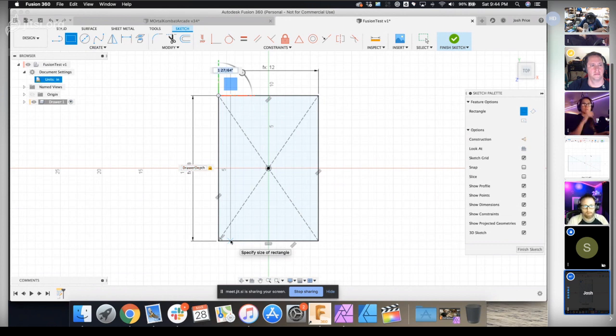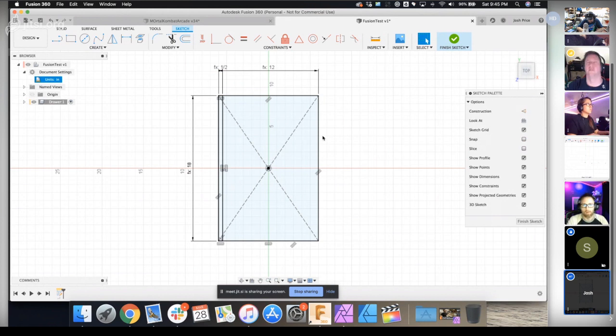I'm going to tab over. You could type in 0.75, or you could type in 3/4 because my plywood is 3/4 of an inch, or you can type in 0.5. That doesn't update. That's not variable. So we're going to use our variables. This is because we're making it out of plywood, like you told me earlier. Plywood thickness, 1/2 inch. Like it says, function 1/2 inch. If you need to change one of these, you can double click on this measurement box and change it.